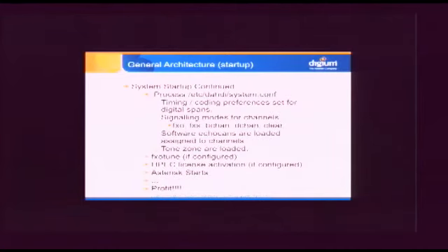So then dahdi_cfg will run after all the board drivers are loaded up, and it'll start processing DAHDI system.conf. And this is the time when the spans have their timing and line preferences set. So whether you want to provide timing to the span, recover your clock from the remote side, whether using HDB3 or B8ZS. Also the signaling modes for individual channels. So for your analog cards, you'll have FXO, FXS, whether it's a B channel or a D channel or a clear channel. But if you're installing a PRI card, you'll know essentially what those mean.